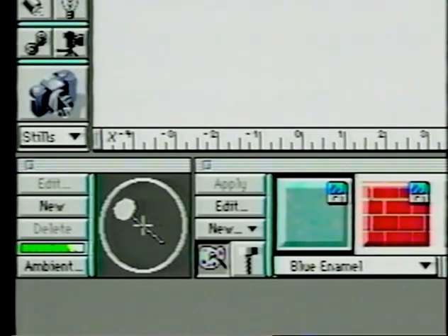The next set are the local light sources, spotlight and point light. The next set, of course, are the linking and camera object tools. And then the final tool is the camera tool, or snapshot, or rendering tool. We move down to the lighting palette. This is where you can set the direction and number of directional light sources. You can click and drag on these objects here in the lighting palette and position them so that they shine on the model from different directions. You can edit, add new light sources, or delete light sources from this palette.